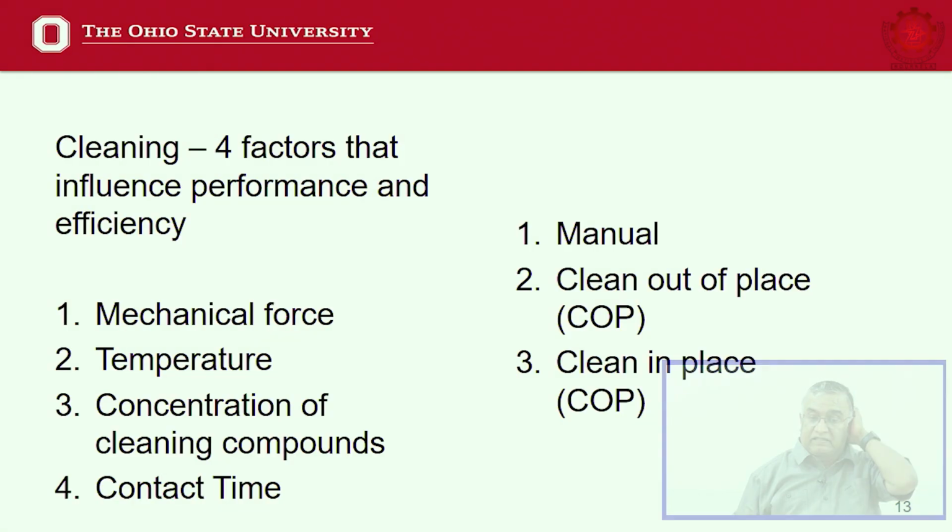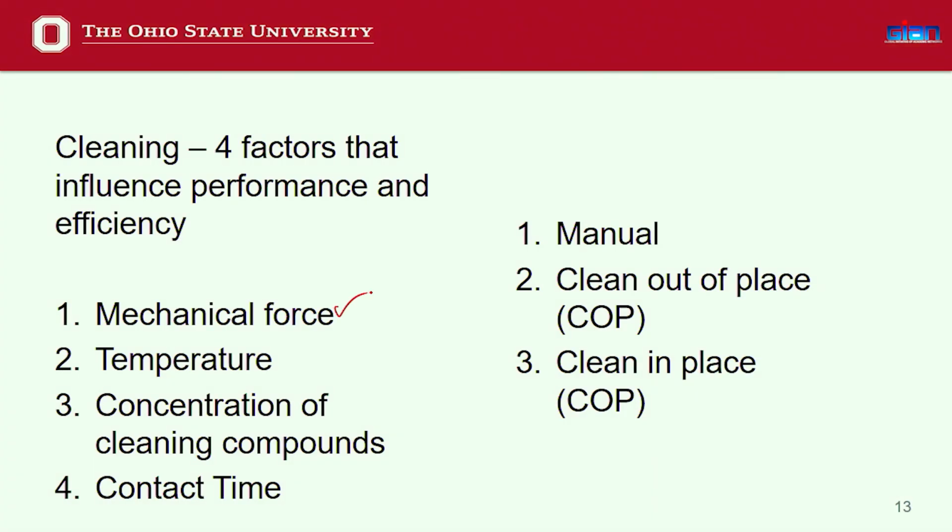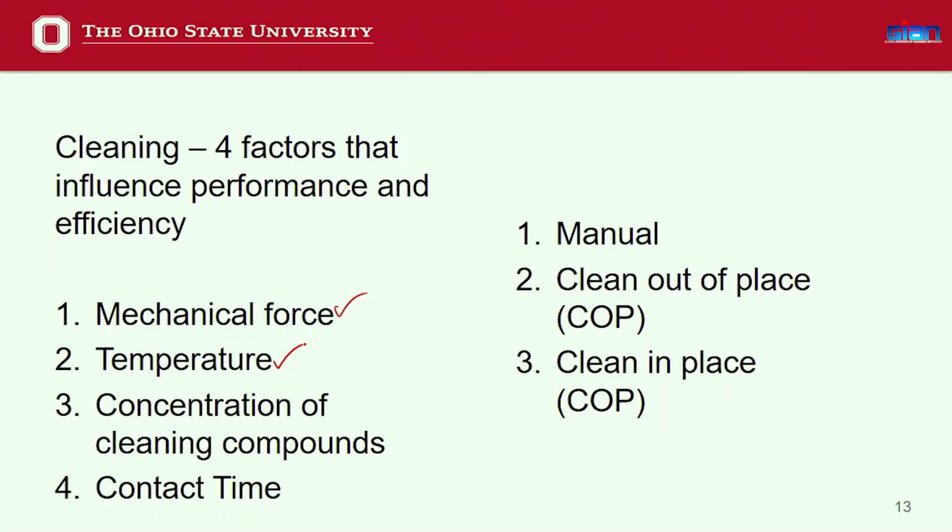So, there are 4 factors that affect the cleaning performance and efficiency. We said mechanical force. We talked about if you are using brushes, mechanically scrape them. So, what type of mechanical force you use, at what temperature you are sending your liquid cleaning solutions, and what is the concentration of the cleaning compounds. Are you using very dilute, or are you going to have very concentrated? So, what is the appropriate concentration, and then how much contact time I have, and so on.